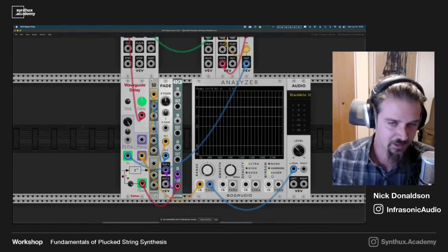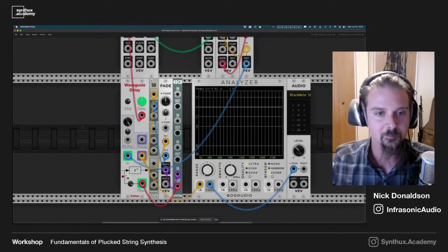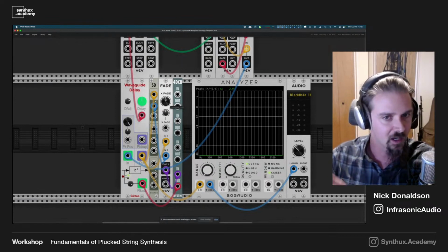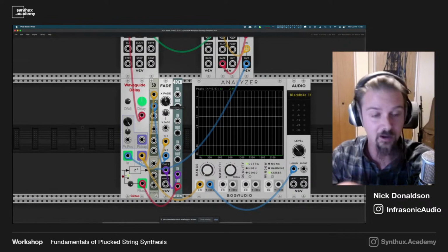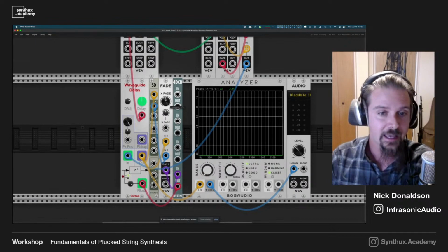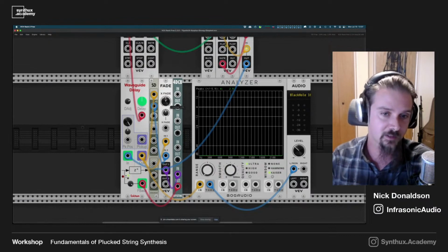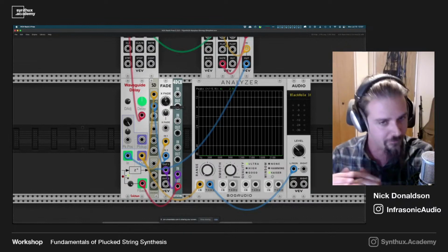And the last thing here is just the DC blocker. That's not really important for the filter. That's important to avoid DC building up in the feedback line. But that's what we're doing. We're just taking the average of the current sample and the sample that we last output, so one sample before that. And by taking the average of these two, it's a very gentle low pass response. So any fast changes in the signal will be filtered out very, very gently.